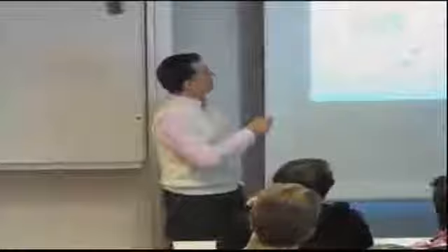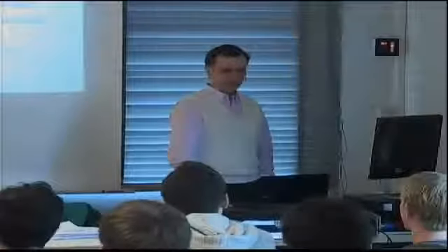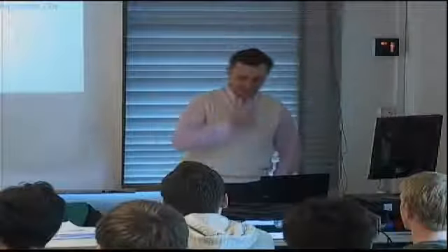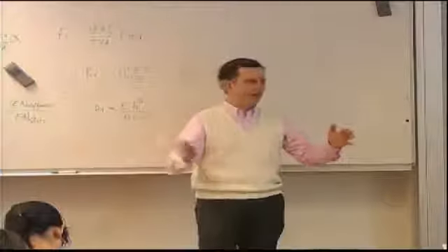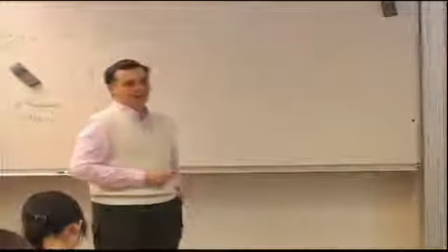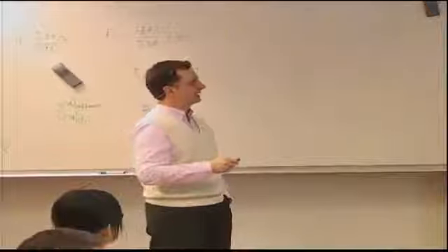You just do a bunch of tests, and you try to fit a multiplier to the test results, and it turns out if C equals 3, that's the number that gives good agreement with the test results. So if the fasteners are spaced a large distance away, S is large, then I can have inter-rivet buckling.